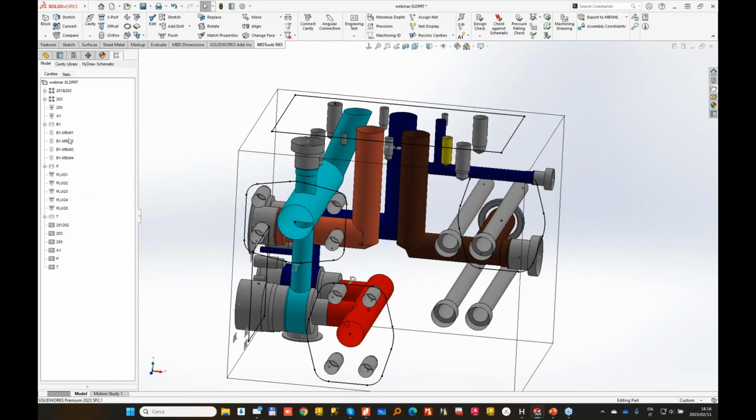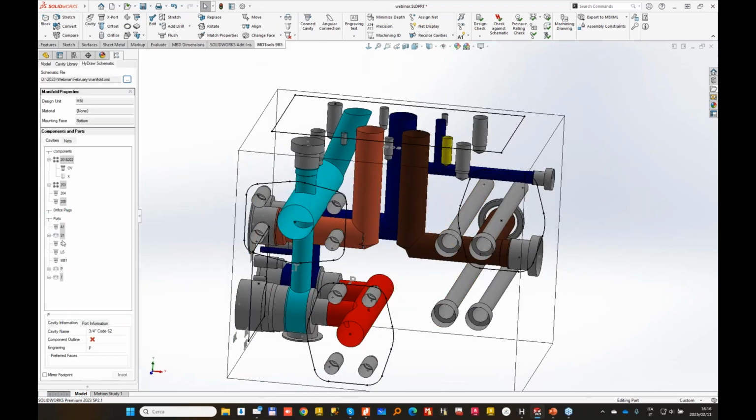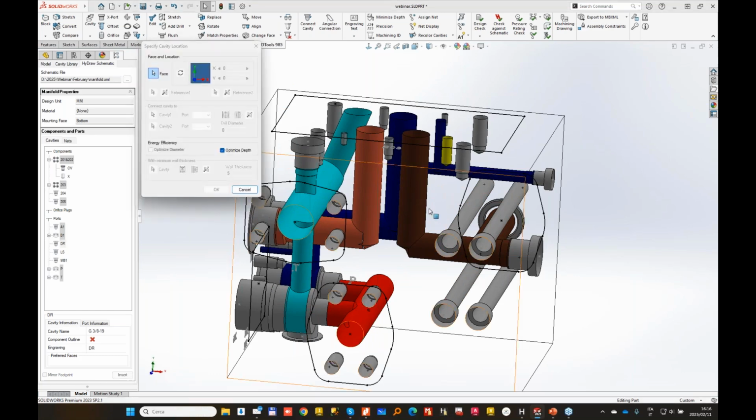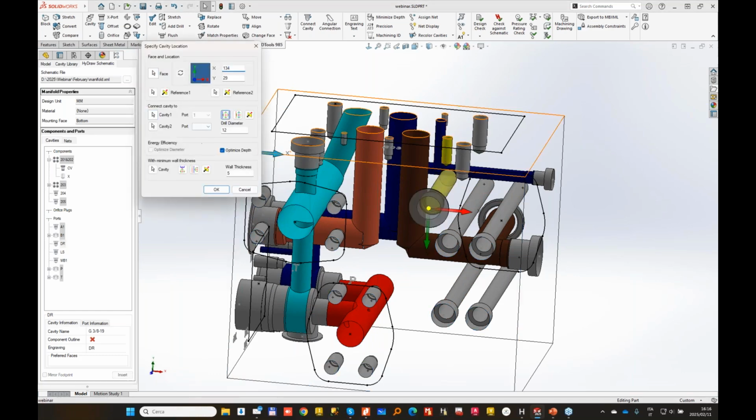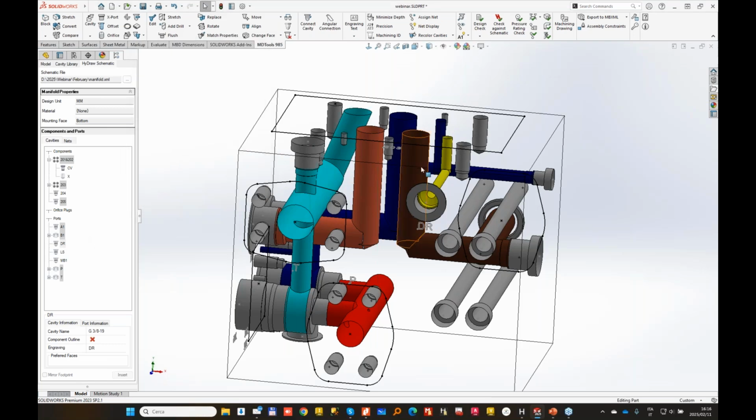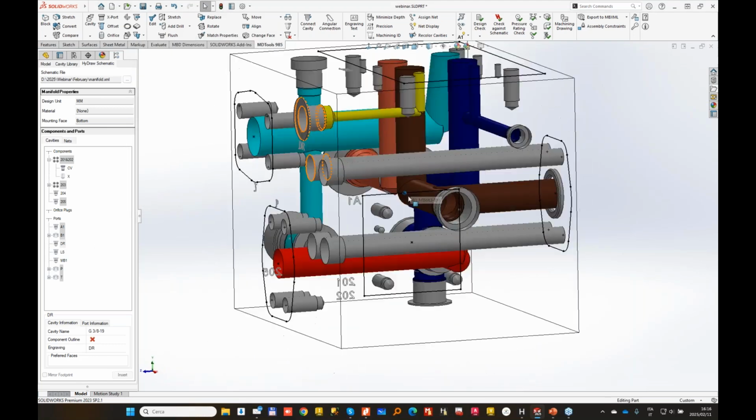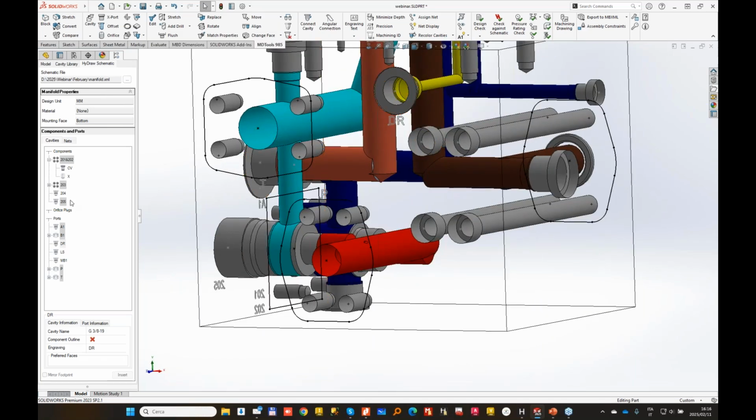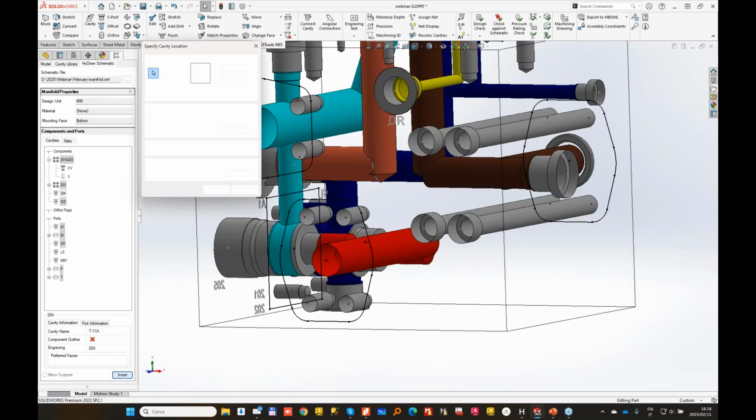This block also has a drain line, which I want on the top face and connect in the center with an 8mm, 6mm diameter. Maybe any position will work. And in addition, I had put a shuttle valve for a load sense signal.